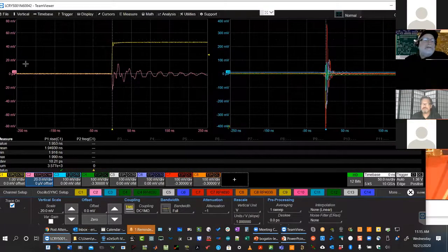First, there's noise, 20 millivolts a division. There's noise, not a lot. You know, it's like a 2 volt, 2.5 volt signal, 20 millivolts. So we're talking about 1% kind of per division noise, but it's got this funny signature. How come? Once again, always pay attention to the device under test.